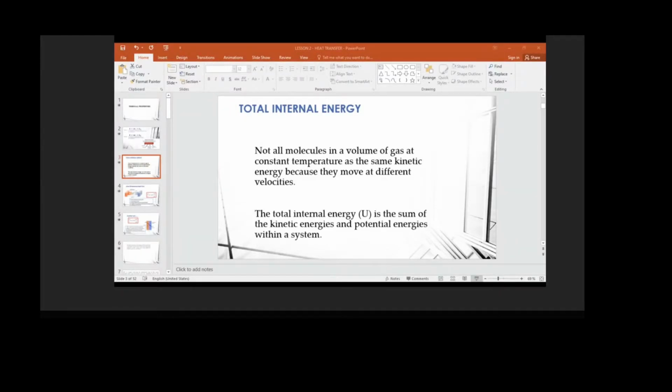Alright, now we're going to look at the heat flow in a one-dimensional aspect. This just means that if we have a metal, we're looking at the heat flow from one side of the metal to the next side. Now here is the equation that we should remember: Q over t is equal to negative k A delta T over dx.